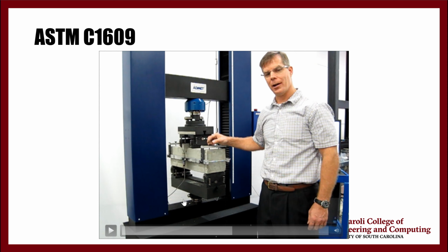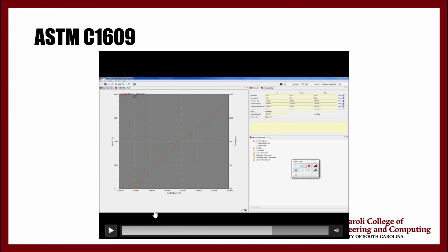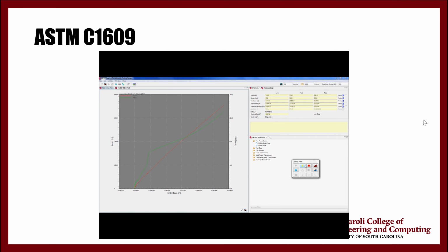These are the supports, and we are measuring the displacement, the deflection here. And it is connected to a computer. You can measure the deflection with respect to load, which is the thing that we want to measure. So we can use the formulas we have to find or investigate the flexural rigidity of our model.